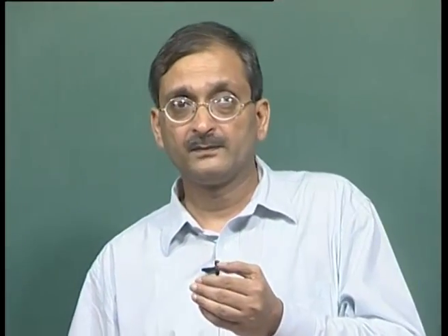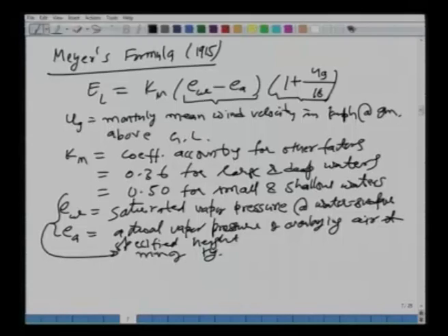All right, because wind velocity is what is responsible for removing the evaporated water from the lake. So, it will depend upon the wind velocity also. So, you see that the Myers formula is accounting for the vapor pressure deficit and the wind velocity, and our aerodynamic method also takes care of these two things, but it has been derived from that aerodynamic method. We will look at that little later.